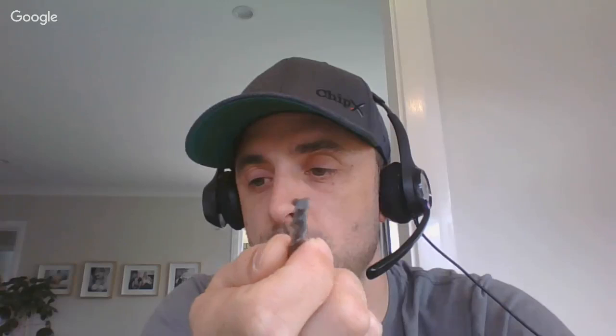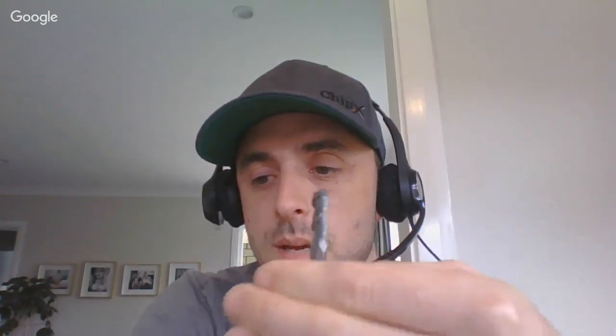Now, if we go too fast, the chip is too big. It requires too much torque. The spindle can't generate it anymore, and we'll start to have problems, which can vary quite a lot, from chatter and vibration to breaking cutters. There's all sorts of things that can go wrong there. So those are the two main parameters when we talk about speeds and feeds. It's the spinning RPM speed and the moving feed. So Brett, do you think that's a fair starting point?